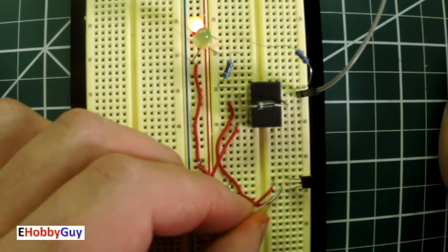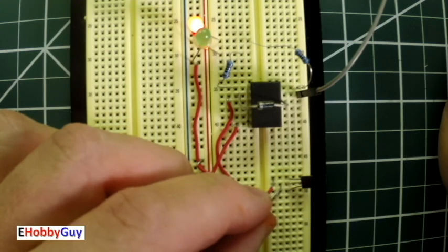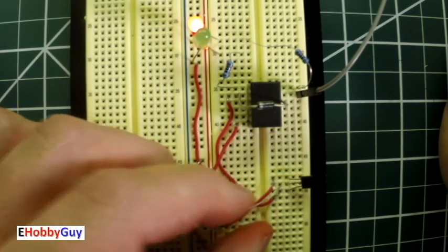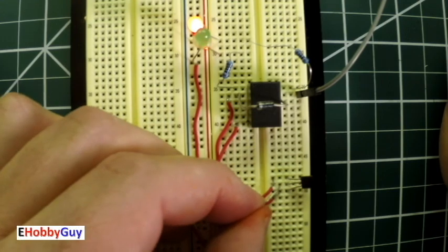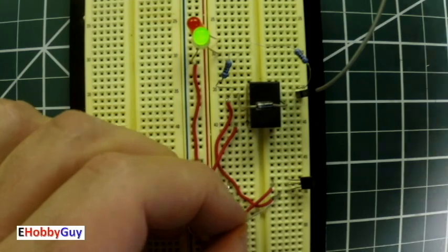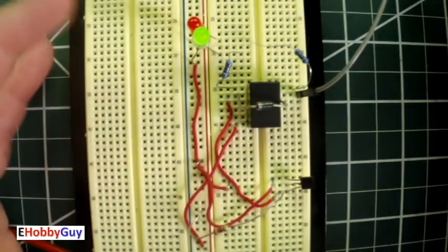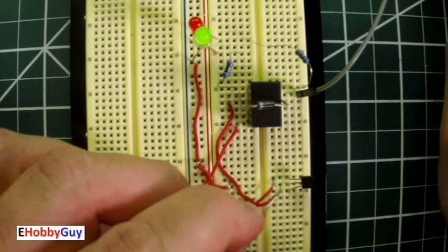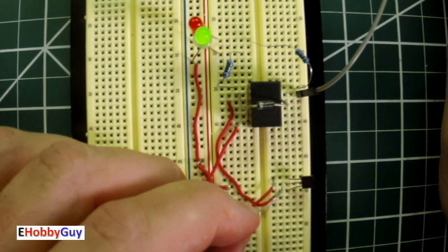And so we can safely use this as a trigger mechanism which can be triggered by any other means. I'm just physically putting it here, but you could have a microcontroller. Anything that's sensitive will now safely trigger the transistor without worry about feedback from any voltage spikes that are getting passed back during the de-energized cycle. So just thought it was worth mentioning, and so let's move on.